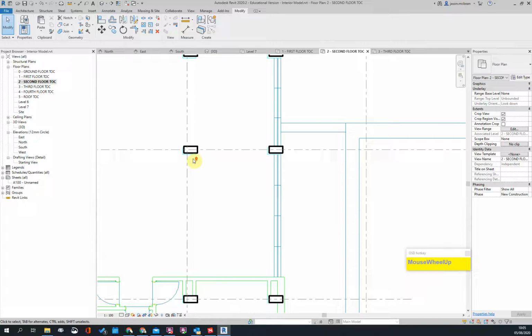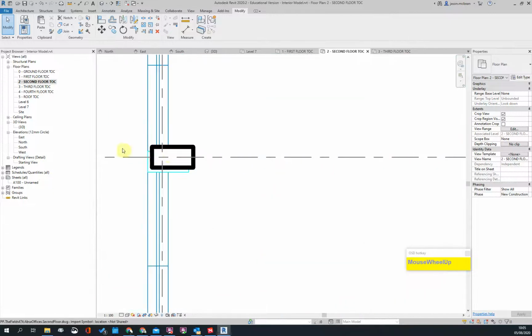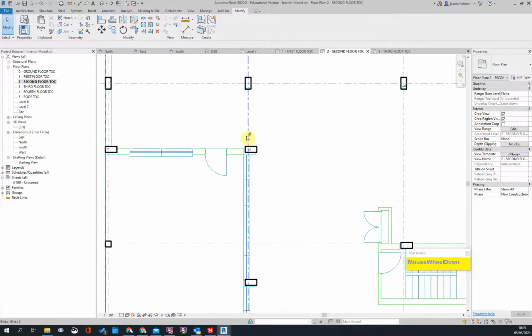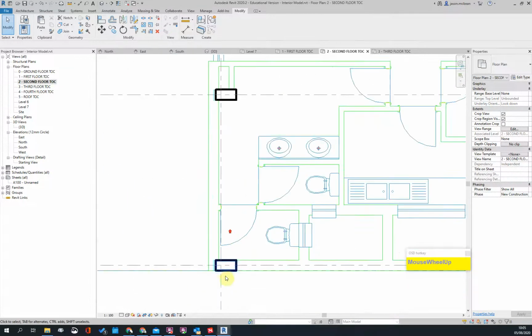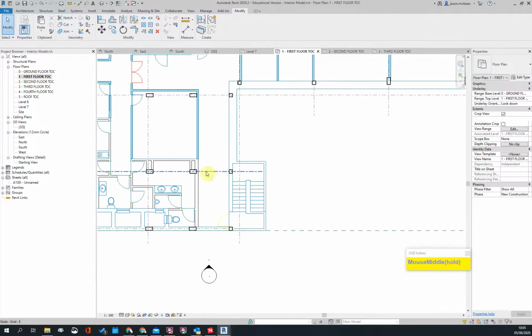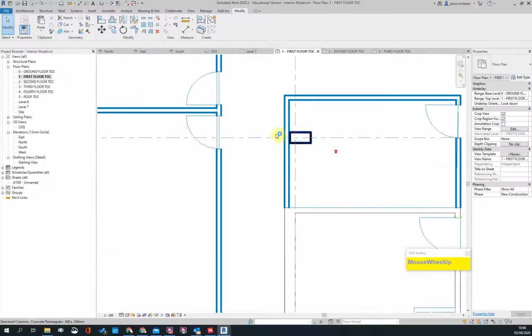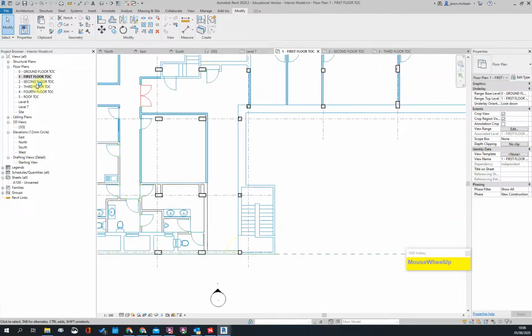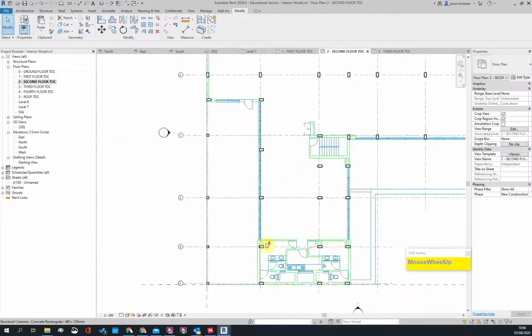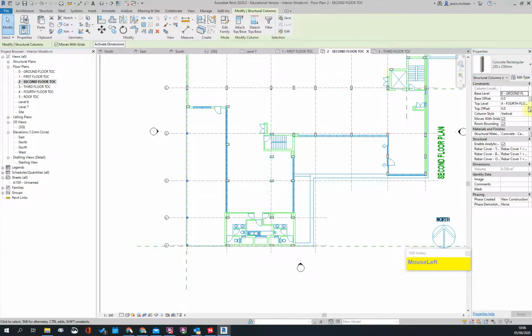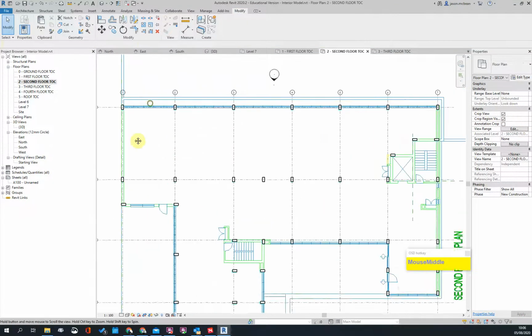And you can see that there's been inaccuracies here. These columns work, and you can see these slight inaccuracies in these models, which is interesting. I can see these all. I must double check because on ground floor I think those things lined up. It's rare that an engineer will move those off. You can see that, so that's an error for the level above. That is a boo-boo. That kind of information we need to note, and then all these columns will also stop. These will stop at level 2 as well. Okay, so the rest of these columns will go up.